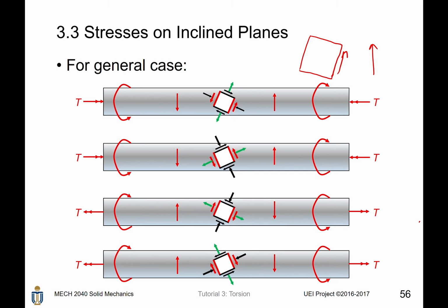But still remember our Valentine's Day joke? Once you know one of the shear stresses acting on a stress element, you can draw the rest of them easily. Then all the shear stresses on this stress element are done and finished. What we need to do is just find the magnitude of the shear stress on this element.